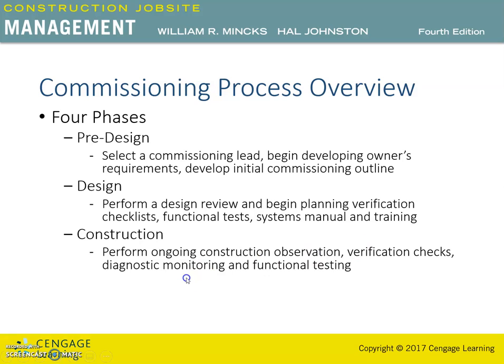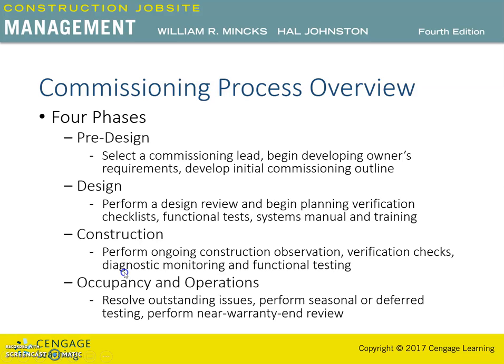Construction phase. In the construction phase, it will be the construction phase kickoff meeting, review submittals, monitor development of shop and coordination drawings, review operation and maintenance manuals, perform ongoing construction observation, perform verification checks, perform diagnostic monitoring, perform functional testing, develop commissioning report and systems manual, develop a recommissioning plan, and verify and review the training of owner's staff.